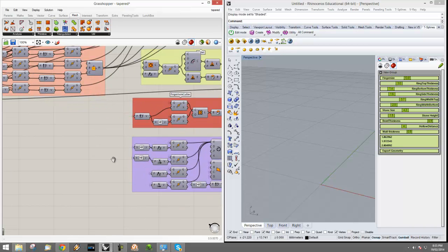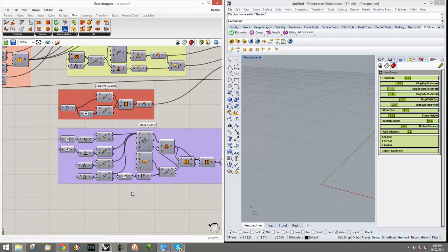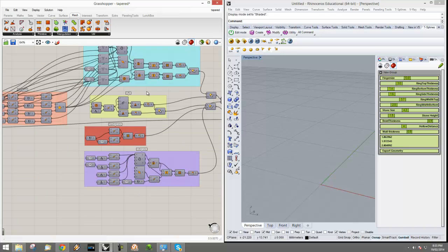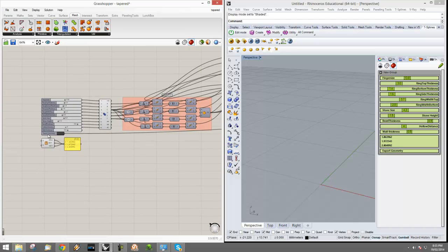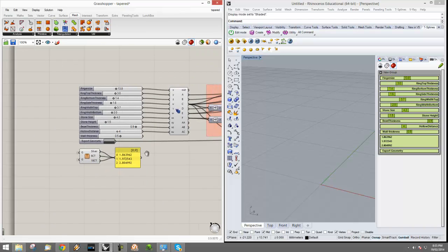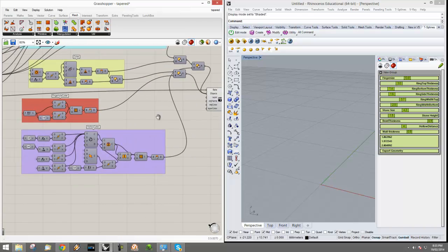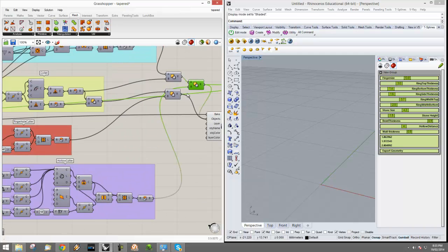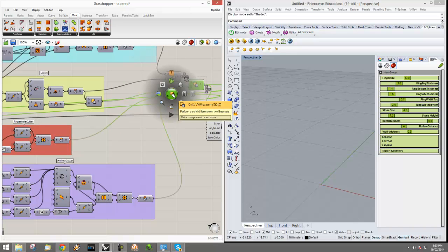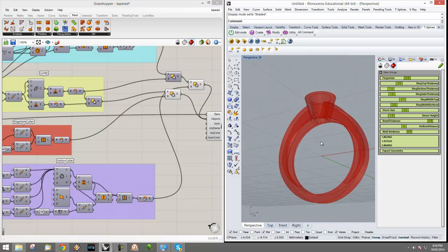All right, and then the hollowing cutter itself is made from the original extruded surface up here before it gets Boolean, which represents a ring, offset in X and Y and Z by obviously the wall thickness amount, okay, and then Boolean from the inside ring. So really the exact same way that you would consider working with Rhino, you work with this. It's just slightly different tools. So I'm going to show all that again, and essentially that gives you this. All right.